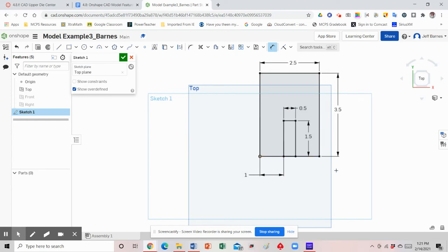All right. Now, the last step before I can extrude it is I need to cut out this middle edge. And again, if you remember from the last video, the trim tool is the one we use to cut lines that we draw. And so I'm going to go ahead and click on the little scissors icon. I'm going to come down to the rectangle I drew and select the bottom edge. And again, I might need to click 2 times to cut the whole edge away. And now it leaves a little gap here. And now I'm ready to extrude.